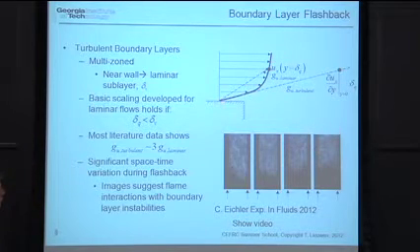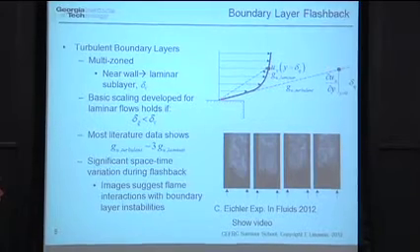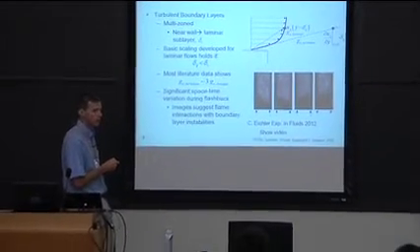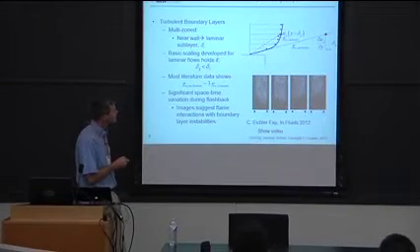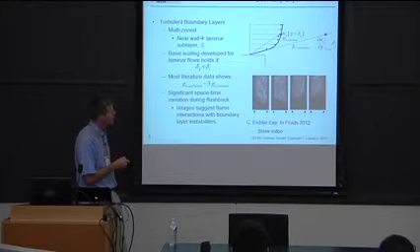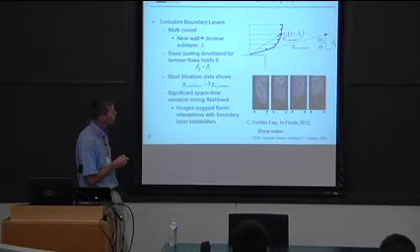And so what you can see is here I have a turbulent boundary layer drawn in. And here's your critical velocity gradient. What this basic theory does is it assumes that your quenching distance lies within this region where it's approximately linear. And if the quenching distance, however, lies outside of the laminar sublayer, you might be up here. And so what you can see is that the critical velocity gradient that you would get would be quite different. If I took dux by dy at y equals 0 times delta q, I would get this number, whereas in reality, if the quenching distance is here, you'd get a very different gradient.